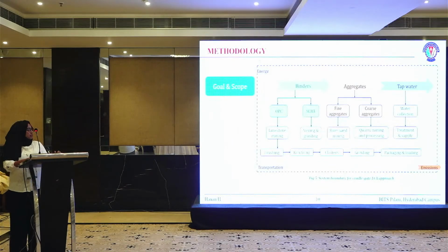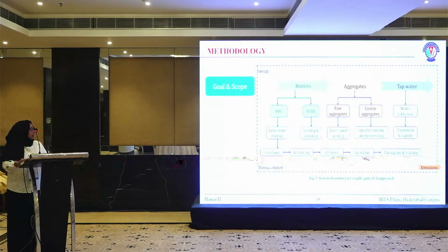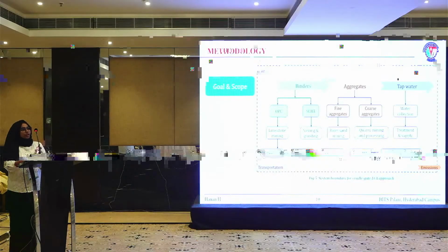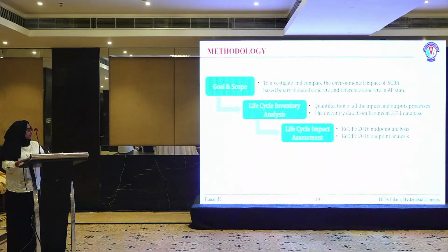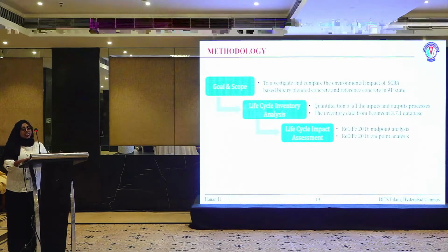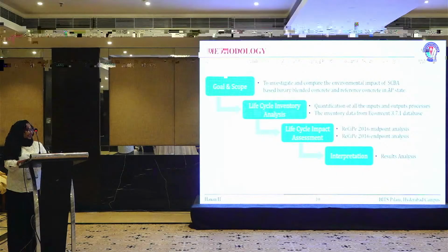Here the cradle-to-gate approach was used, and the system boundary is shown in the figure, which includes all the emissions and the energy utilization from the raw material acquisition and the transportation, till the concrete production stage. Unit processes within the system boundary are required to create a product system. And the third phase is the life cycle assessment stage. Here ReCiPe midpoint and endpoint assessment were used, and the OpenLCA software was used for the analysis as well. The final phase is the result analysis and result interpretation stage.